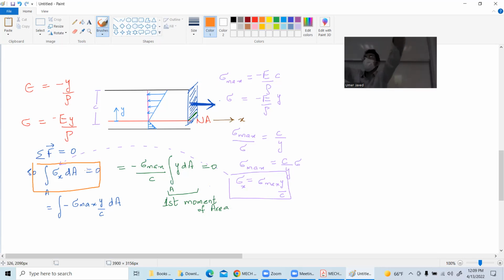So you see, hang on, please focus. I'm bending this, right? Because this is a beam. I put a load. This object is under bending, or it is being bent like this. Either way, I have told you that the stress flows like this in the x direction, right? Stress flows in the x direction, right? Okay. So if I ask you what is the force that this object is subjected to, you will tell me that the stress is acting in the x direction, multiplied by this area, right? So stress x multiplied by this area will give us the force that is being flown into the x direction.